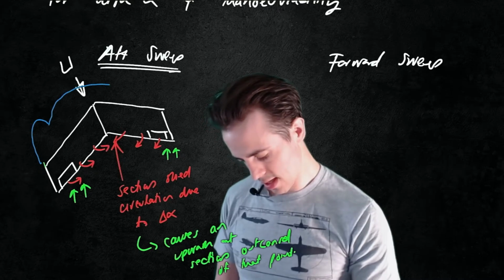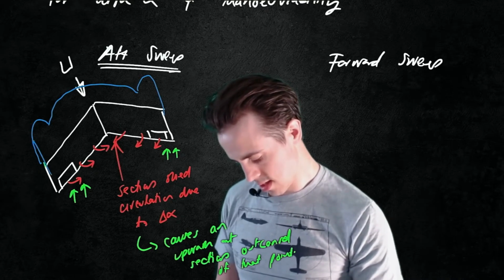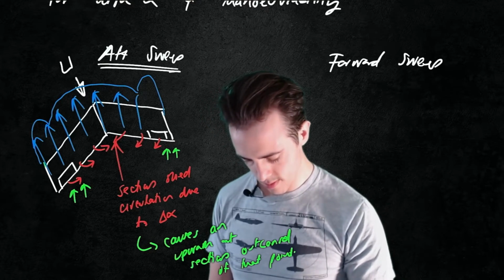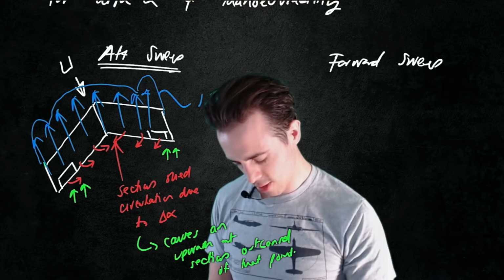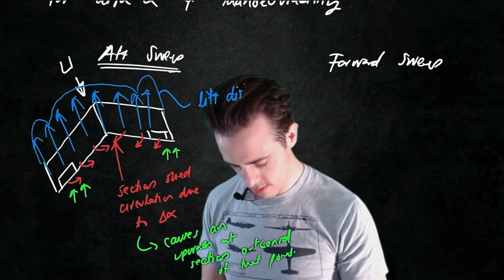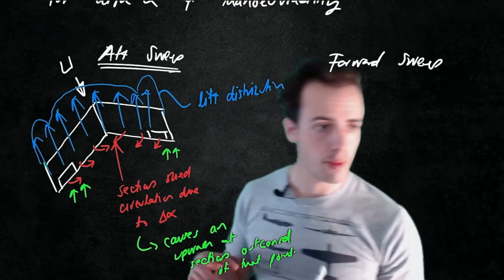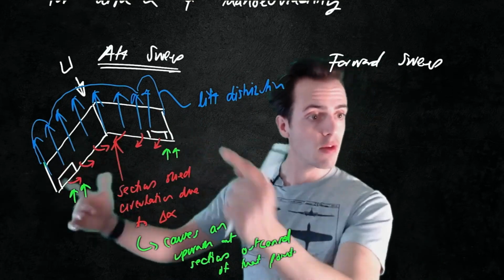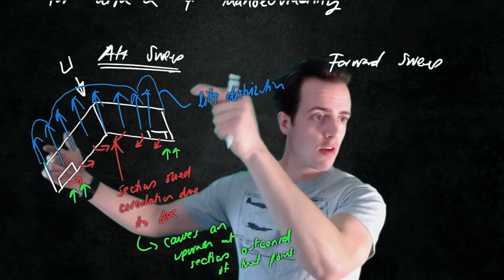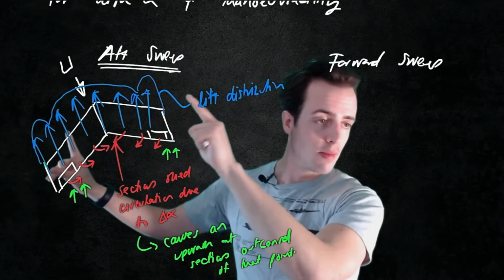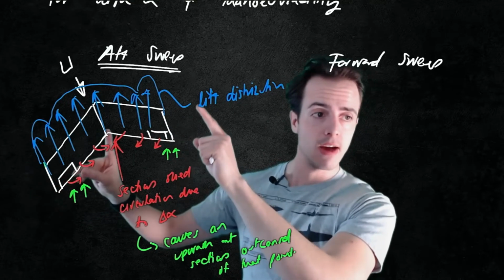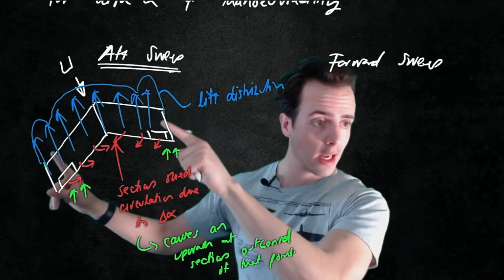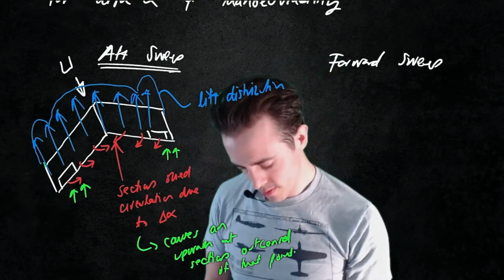So we see this peak at the tips, so this is my lift distribution. Because of this upwash at the tips, because of shed circulation on any section inboard of the tips, we see this increase in the lift distribution, increase in alpha, and then what this is going to cause means the tips are going to stall first, because when we have any velocity perturbation, any alpha perturbation, you're more likely to see a tip stall.